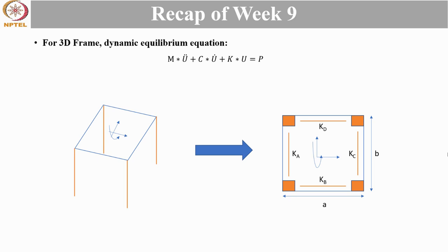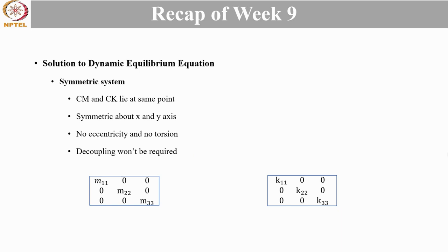Like in the x direction, if the force is applied in the x direction, you can see in the figure kd and kb will show opposition because they are in plane, parallel to the force, while out-of-plane columns, that are kc and kb, won't show any opposition. And to oppose rotation, moment is considered with respect to the center of mass. So based on these concepts, we formed a mass and a stiffness matrix.